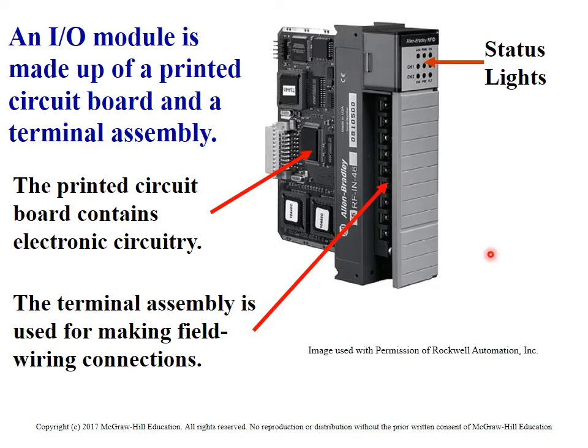Status lights. This is some good information. Each one of your input cards will typically have a status light. When you close the contact to one of these terminals, you'll see the light come on in front. That gives you immediate acknowledgement that the input is coming on, without having to open up the PLC or the laptop to figure out if that input's coming on or not. If you can see that signal come on in the light, then you know at least that input is working properly.